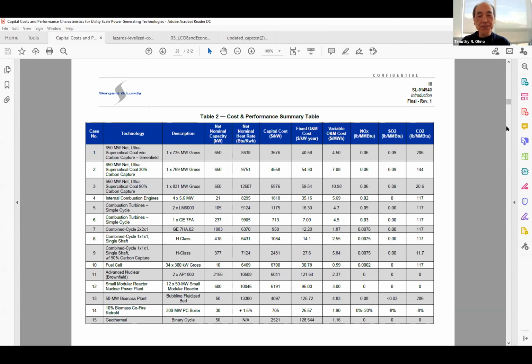Abdullah, did you have a question too? Oh, sorry. Yeah, I was going to say, just to be clear, is it going to be in kilowatts per hour? No. So your answer for the LCOE is going to be my cost per unit energy, so it should be in dollars per kilowatt hour or megawatt hours. The cost per megawatt hour is going to be 1,000 times higher. I meant for the fixed O&M cost. It's not dollars per kilowatt hour. It's in dollars per kilowatt in 1 year.